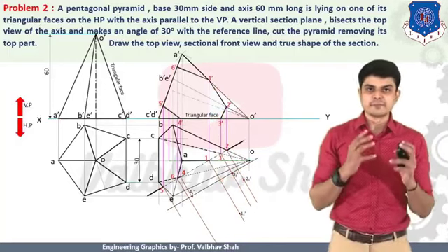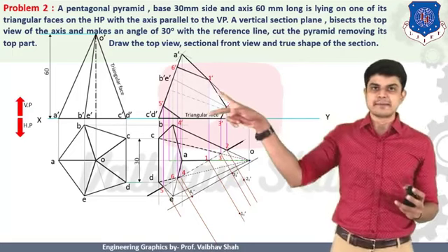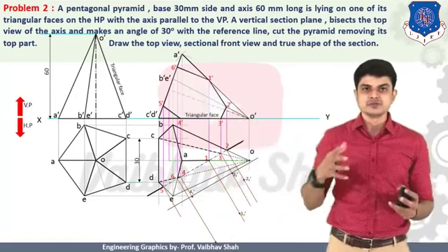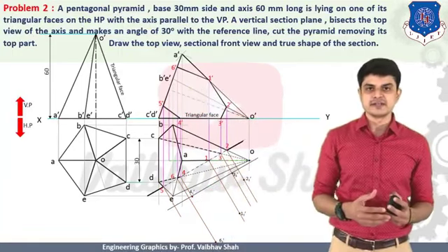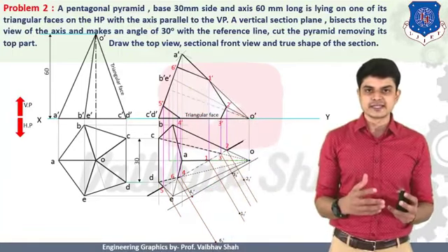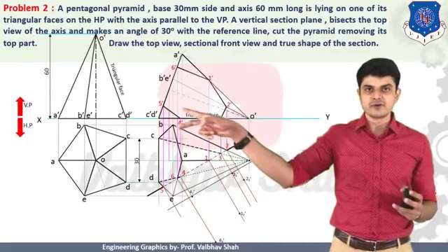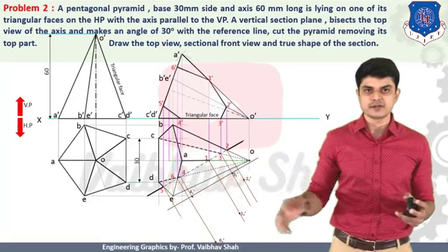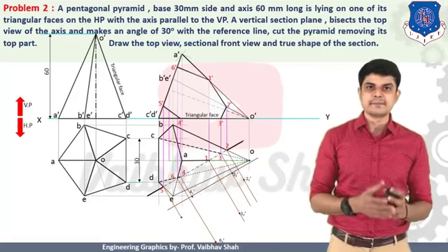Now let us plot point number 6 first. So you should take the dimension of point number 6 from your xy line, and you should put point number 6 dimension here. So you will be having your point 6 generated there. And thereafter finally you should take the dimension of point number 5 into your rounder from your xy line, and you should put your rounder on this inclined line, and you should plot this point. So you will be having your final dimension generated.